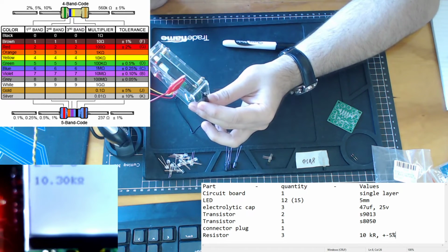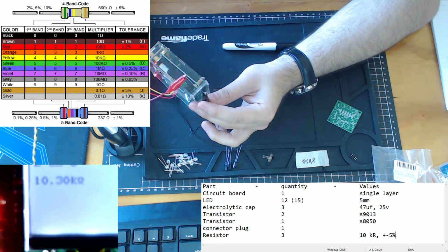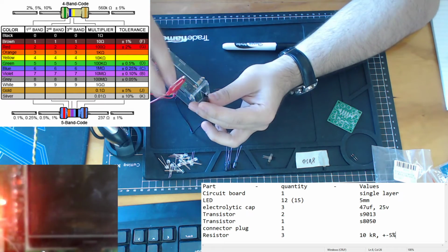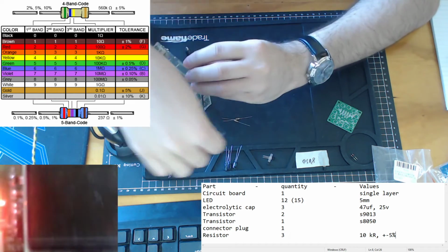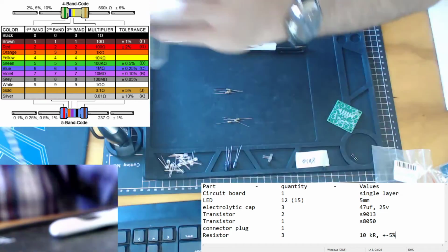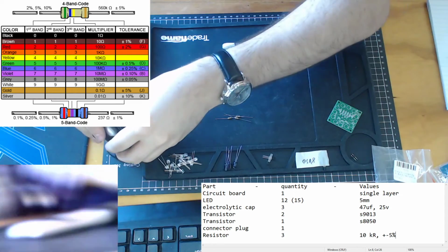So that 0.3 is part of that plus or minus 5%. It just means we know our resistance value is based off a lot of factors. The material itself has its own resistance, but its cross-sectional area, even the temperature can change. And it's cheaper to make a resistor with a lower resistance, and the other resistances will change their value with that as well.